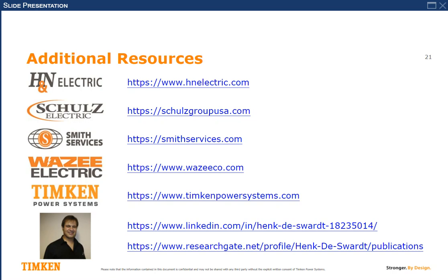But the repair company should actually pick that up on test already. When they run the machine after the repair, they should have seen that. I mean, it's literally a humming noise. The machine will have vibration on the core. You can measure it, and you will hear it, and it's voltage dependent. It happens occasionally, and when it happens, it's not too difficult to process. Even on a machine that's been repaired, you can open the connections, add a couple of wires between the different parallel circuits, equalize it, and boom, the problem is gone.